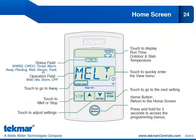We have sensor, and that would appear if you are using the Tandem snow ice detection function. And track, if this 654 is tracking the operating time of the zone that has the automatic snow ice sensor 090 or 094, then the word track would show up on the screen. So this status field is very helpful to tell you at a glance what is happening in this snow melt zone.